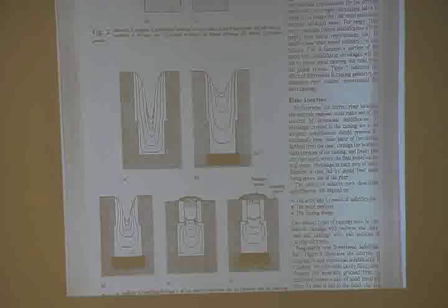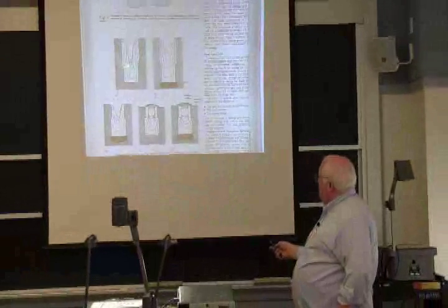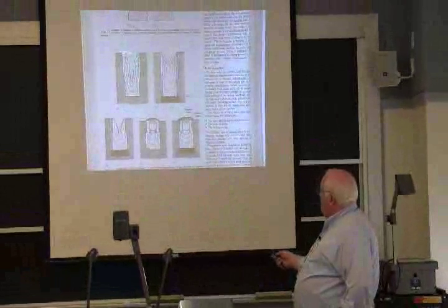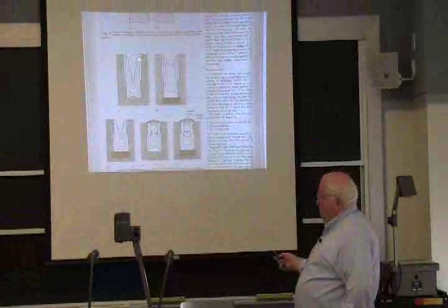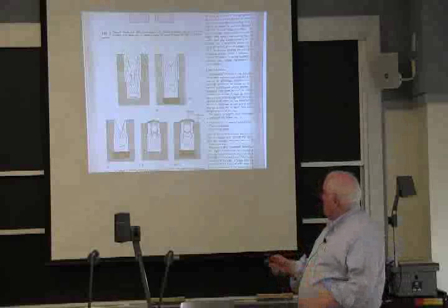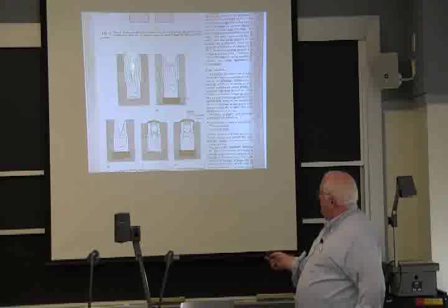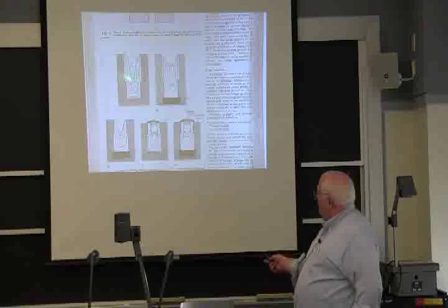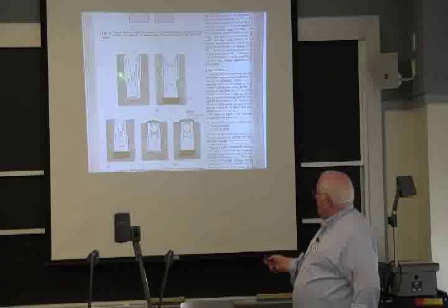Quite often for steel or cast iron, people used for thousands of years sand, silica sand, that you form the shape of the part you want to make, but you have to pour in this extra metal. Initially you pour it in liquid all the way to the top here, but because of shrinkage you get this pipe. It looks a lot worse, but if this is a cylindrical part, the void volume in the center is small as you're shrinking the radius down to 0, but you can end up with a pipe that is deeper than the actual casting.